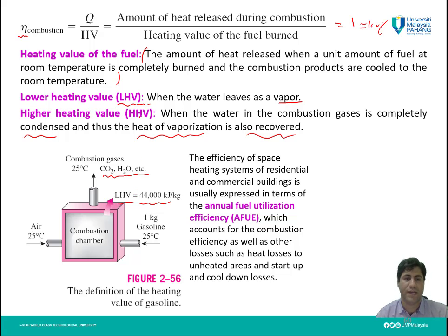So LHV and HHV, or lower heating value and higher heating value, will be different for a fuel in a combustion reaction. The difference is only in the phase of the produced water from the combustion reaction, because it is effective on the amount of energy which we can get from the combustion reaction.